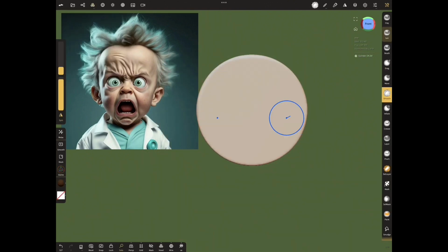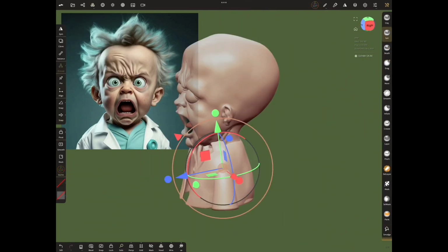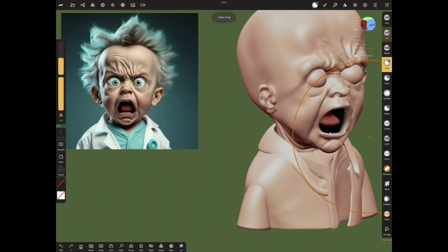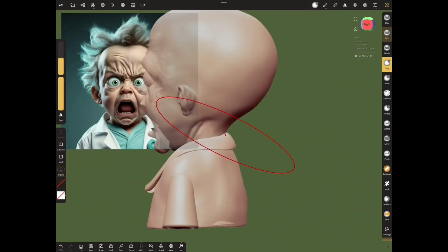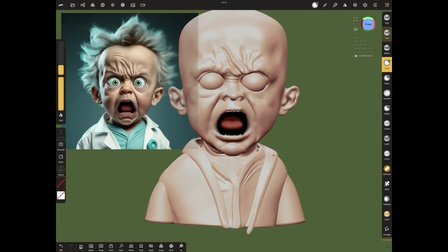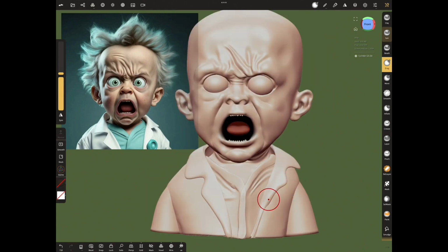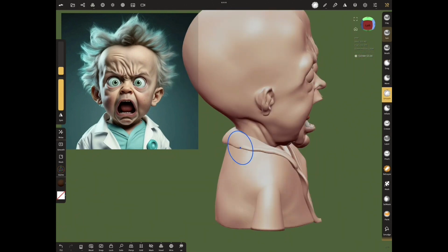Yes, for the collar of the apron, add a cylinder from the scene menu and cut the middle using the trim tool. Give the form of the apron, form the collars of the apron and merge all the pieces, with the arms, using voxel merge. When creating the clothes, add and form separate pieces like this and then merge those pieces.